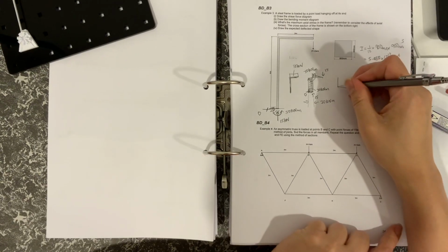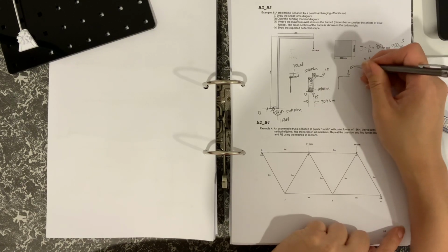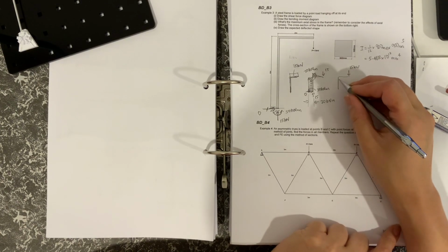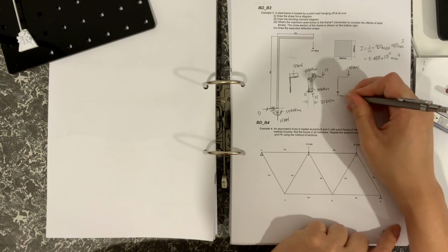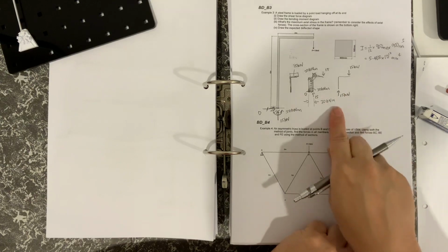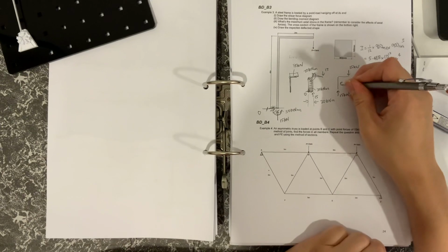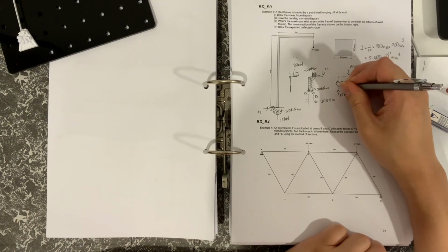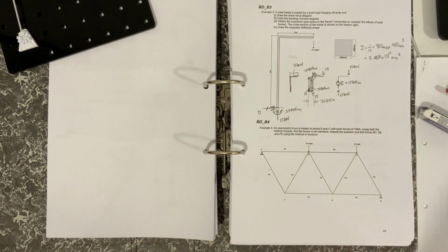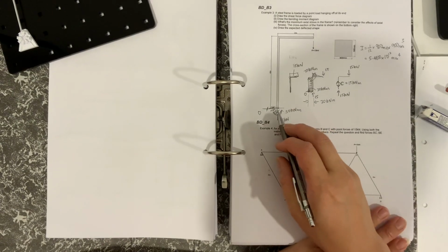Let's now draw the axial force diagram. So we've got that 15 going down there, 15 kilonewtons, and then the axial force, this guy is going to be in compression because you've got the 15 kilonewtons up there as the vertical reaction. So this is definitely going to be in compression, and if you remember from the lecture, we would show the compression force like that. So it's going to be compression of 15 kilonewtons, of course. So the maximum stress is going to be right at the base.